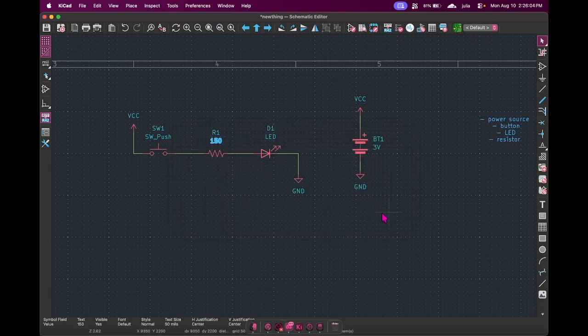Alright. But yeah, that's how you can figure out what values, for example resistor value, you want to use. So what value should we use? 150. Yeah, because you want a current of 0.02 for your LED, and we're going to be using coin cell batteries for 3 volts. So we do 3 divided by 0.02 to get 150 for your resistor. Yay! And that's pretty much the only component we have to worry about, just what our resistor value is and what our battery value is.